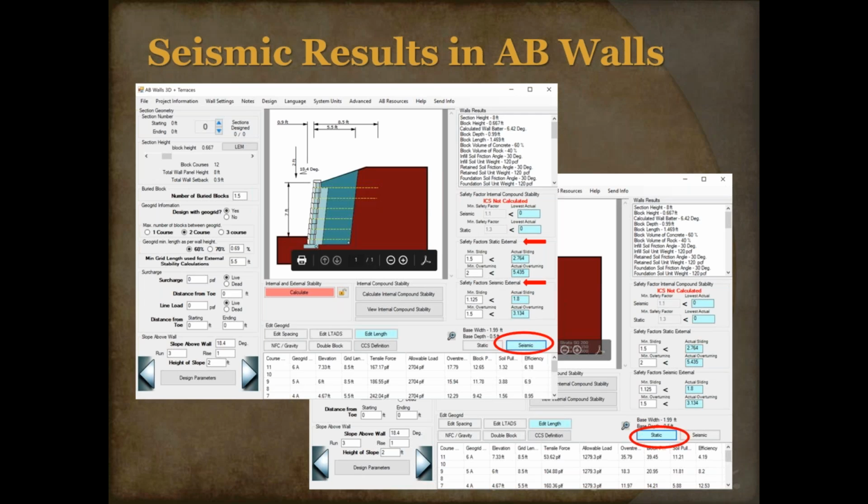Great question here again. I did get another one. Is there a height limitation when using the 3-inch maximum deflection? No, that's very insightful. There is no max height. That 3 inches of deflection is being used on a 3-foot high wall, or a 33-foot high wall, or a 53-foot high wall.